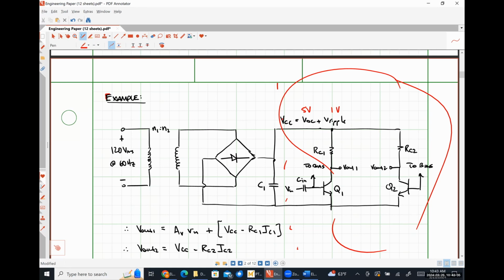This is just a practical way of doing it, because this is, as a loose approximation, the internal circuitry of what a DC power supply actually is. It takes AC from the wall, steps it down to some allowable level, much less than 120 volts RMS. And then we use a rectifier circuit to make that approximately DC. But now we've run into the point where we're constantly perturbing our supply voltage for our amplifier, because inherently converting AC to DC gives us some amount of ripple. Yeah, so you're looking at it the wrong direction.